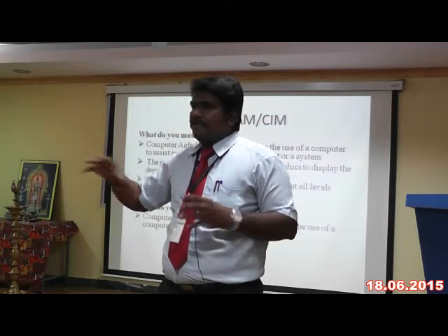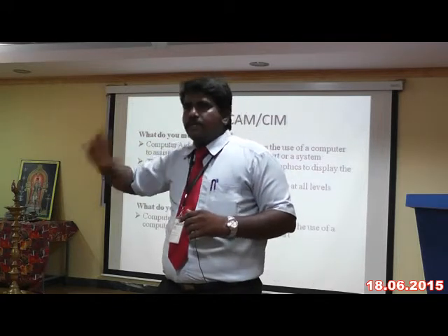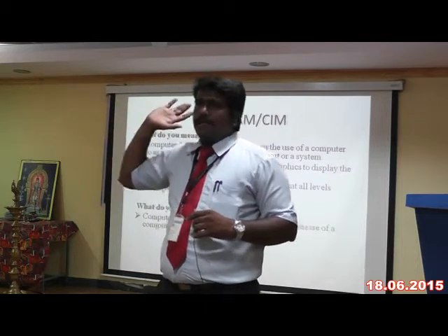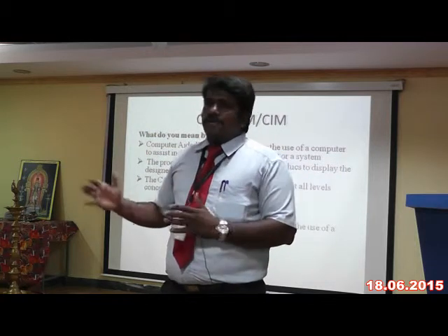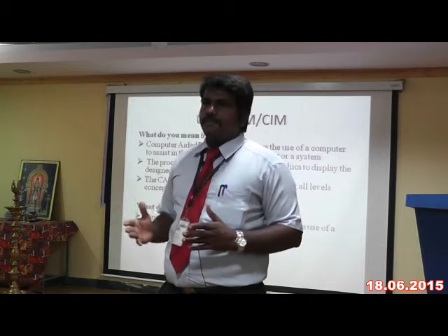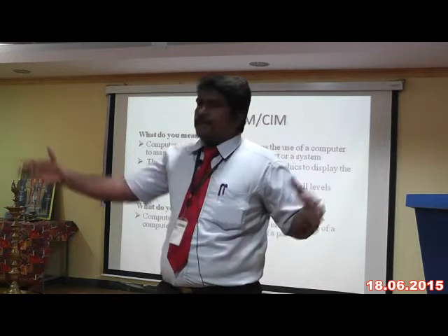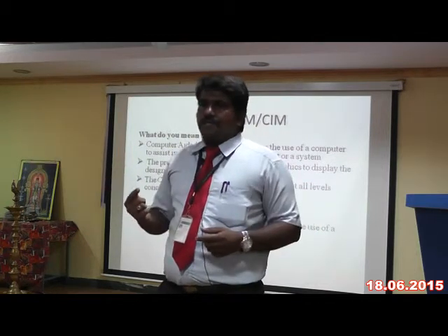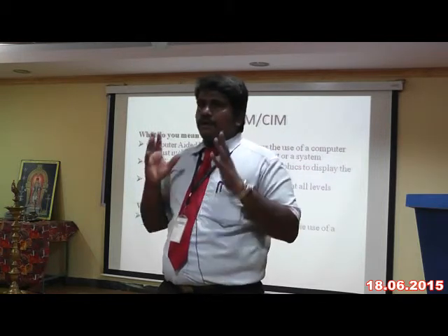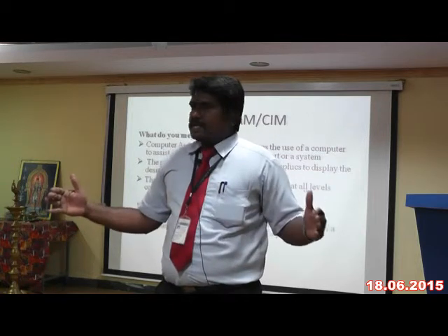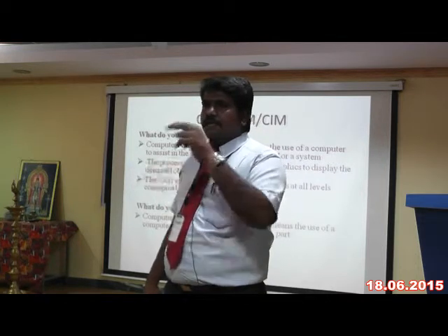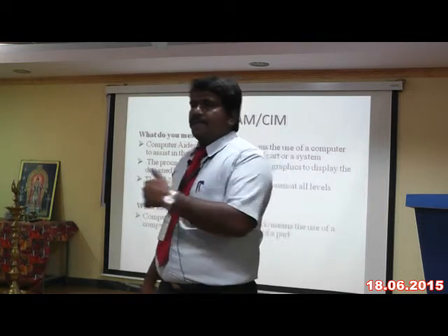Finally, it would be put into heat treatment, which would be kept in a separate shop floor or separate unit. But when the process is done continuously, step by step, stage by stage, that is said to be the flow shop. And a hybrid flow shop means, suppose you have 10 stages, and any one of the stages has more than one machine. It doesn't mean all the stages should have more than one machine. All 9 stages may have a single machine, but if any one stage has more than one machine, then that type of shop is said to be a hybrid flow shop.